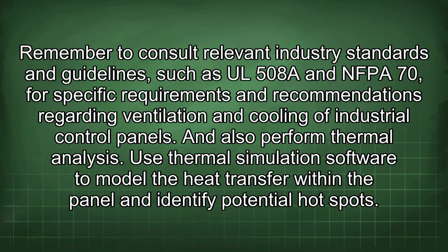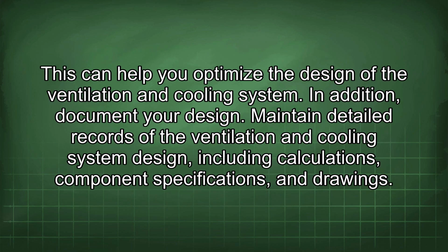Remember to consult relevant industry standards and guidelines such as UL 508A and NFPA 70 for specific requirements and recommendations regarding ventilation and cooling of industrial control panels, and also perform thermal analysis. Use thermal simulation software to model the heat transfer within the panel and identify potential hotspots. This can help you optimize the design of the ventilation and cooling system.